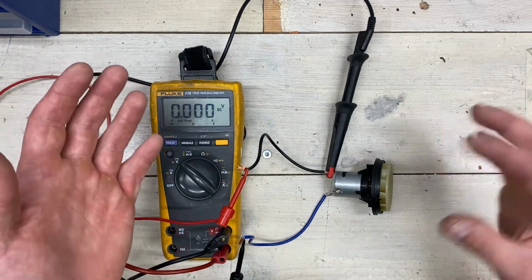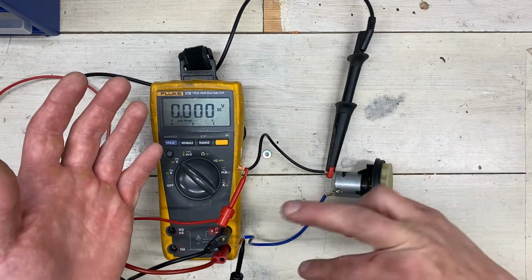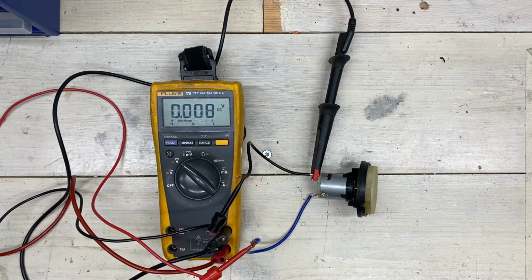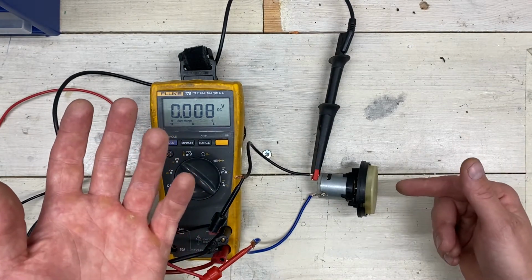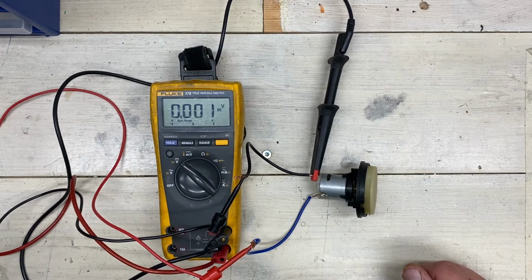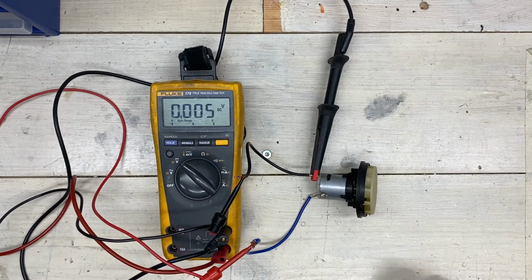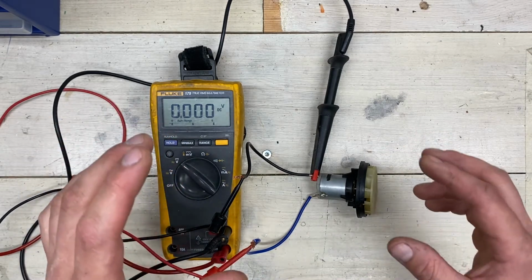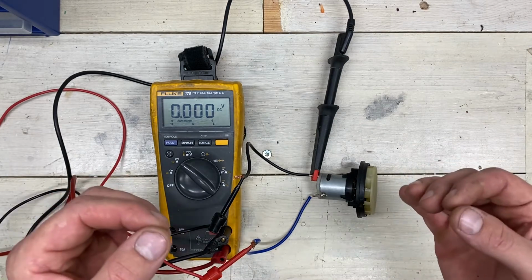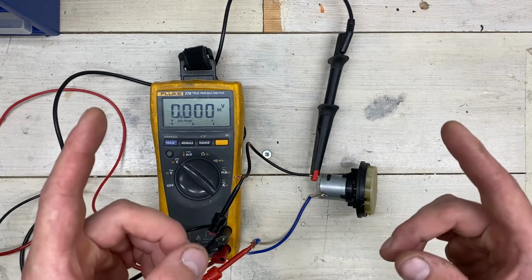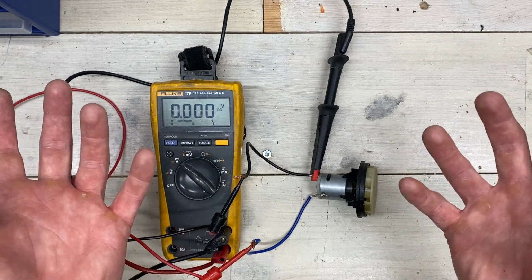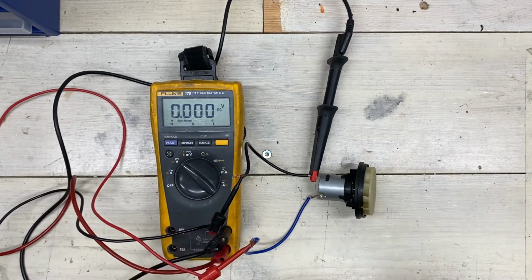It is also really easy to reverse the rotation of a DC motor. All you have to do is swap the polarity. I don't know if you can see it, but it is rotating in the other direction. Now this can be done in several different ways, either using relays or contactors, or using an electronic device called an H bridge. And I will explain what that is in the next episode of this series when I talk about motor control and drivers. But let's move on to something a bit more complicated than this one.